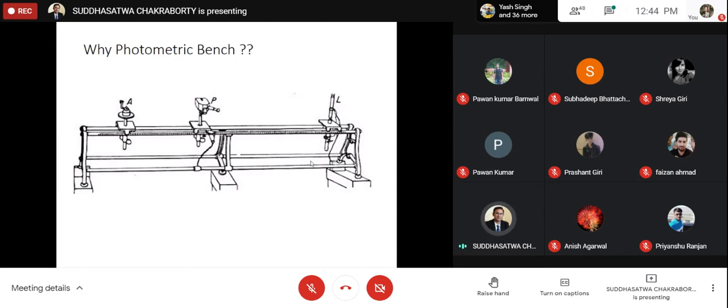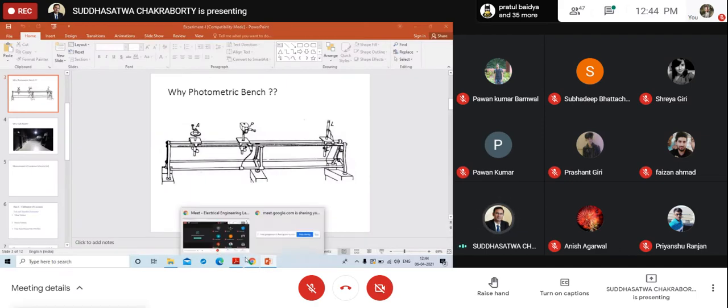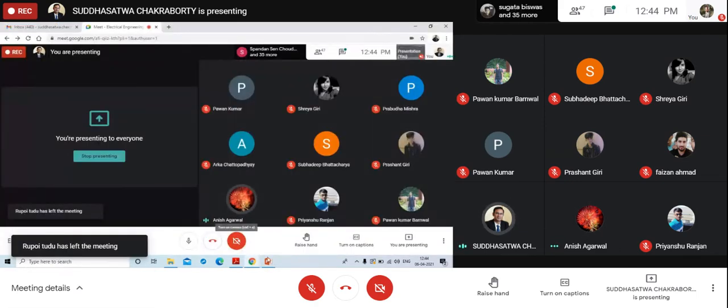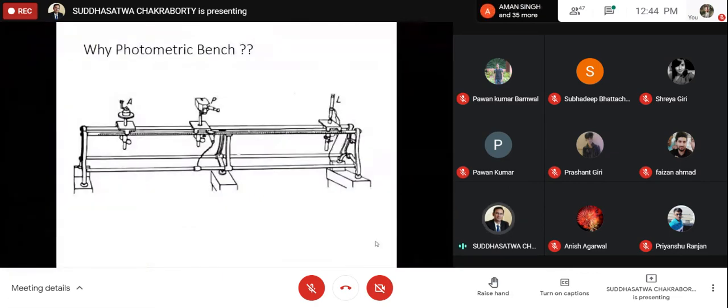That can be done easily, but will it help me to develop the calibration curve? Why not, sir? I am asking you why it happens. Because once you have put your source on and fixed your position, you are going to get a single data. Out of a single data, how can you plot a calibration curve? The calibration curve deals with the entire range of measurement for which you are going to use your measuring instrument.